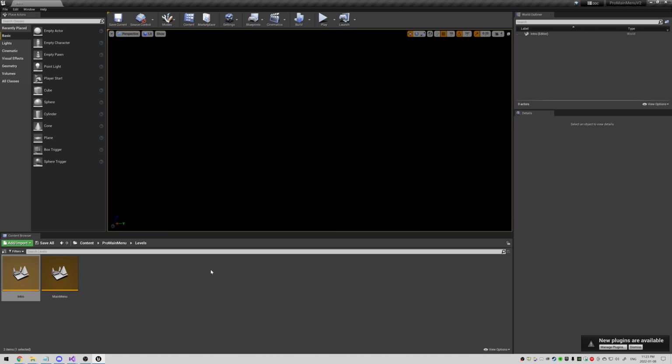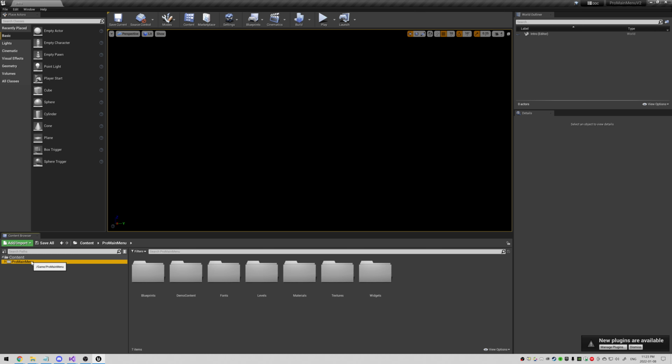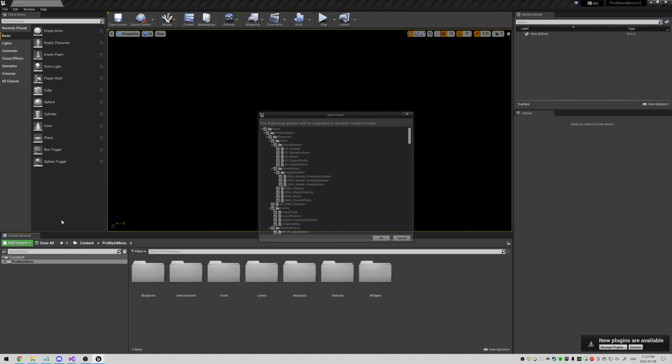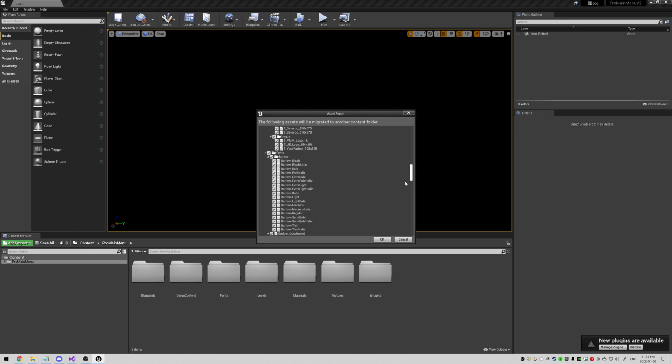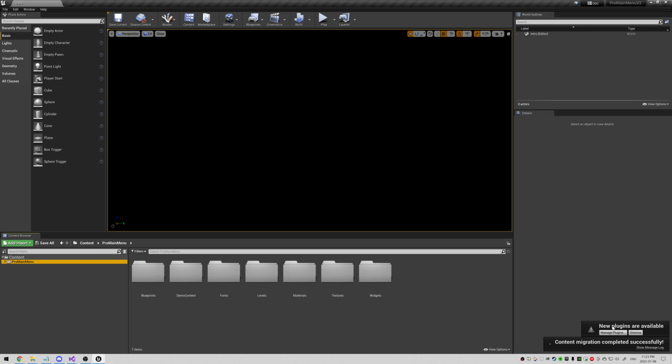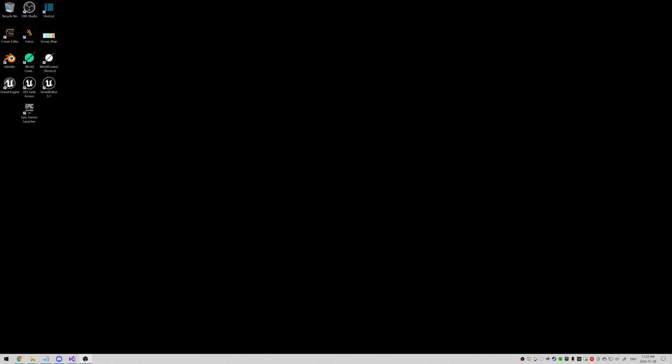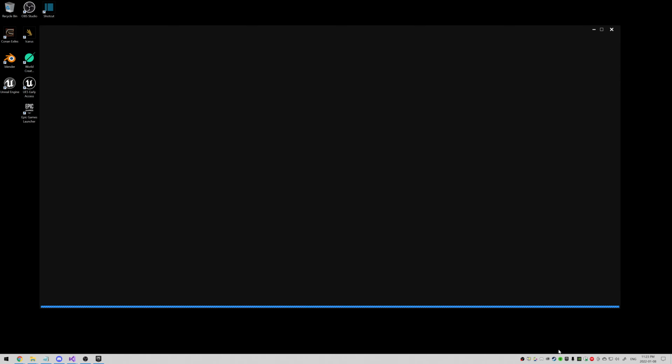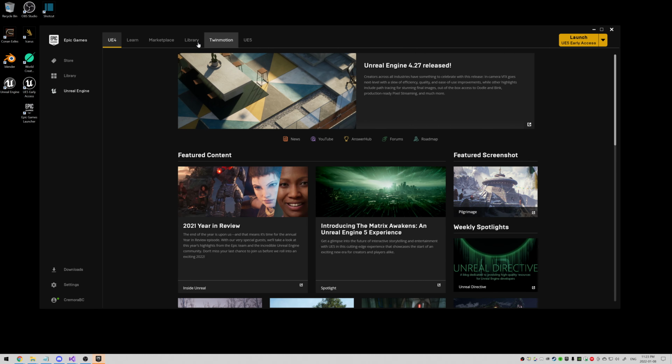Alright. So what we want to do from here, we'll just go to the Pro main menu, hit migrate, make sure everything's selected, click OK, jump into the content folder of our project, migrate complete, okay, and then we're done with that. So now we need to open up our project again.